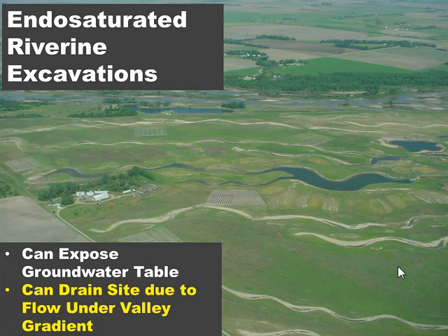So the technique that should be employed, if we're contemplating doing this type of excavation to expose groundwater, is to keep the length of those individual excavations short and separate them so that we have remnant material in between, and maintain them as individual, short, discrete ponded elevations, and we will maintain that groundwater elevation in affected sections of the valley.